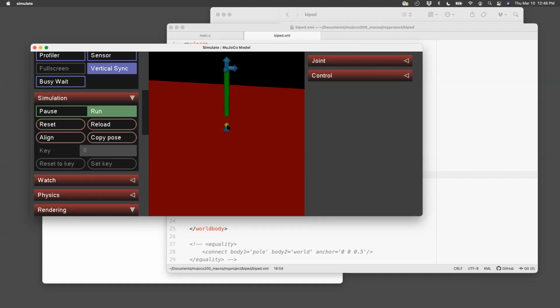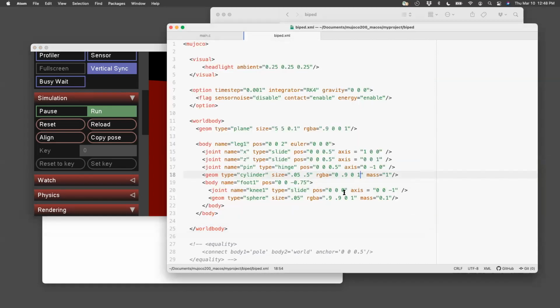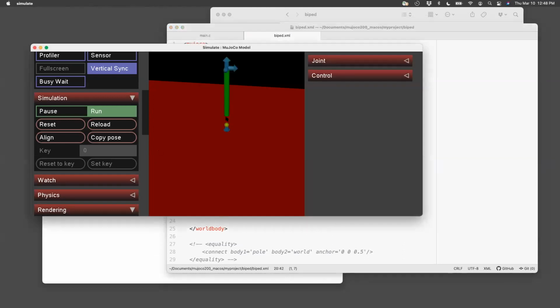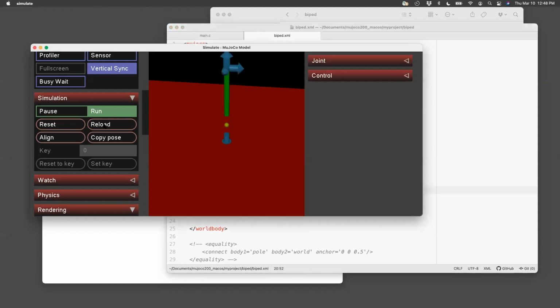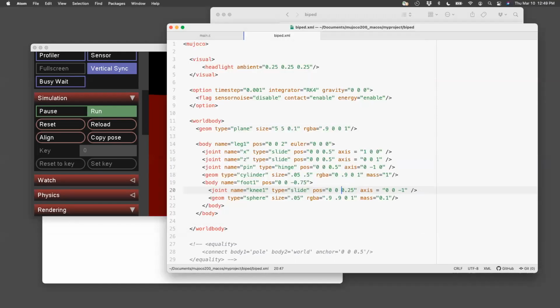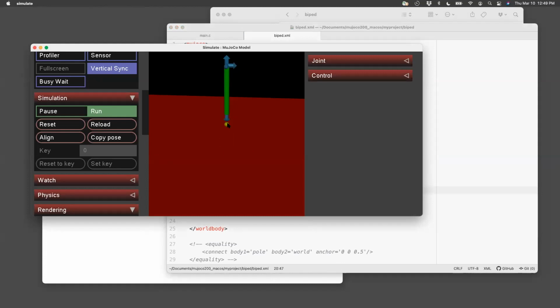It's a little odd that the axis of the sphere is sitting right here. Maybe I want the axis right at the tip of the cylinder. So right now it is set to 0, 0, 0. Okay, but I want it to move up. And remember that this distance is 0.75. So if I want to move it up, I want to probably move it by negative 0.25 because that distance is relative to this point first. And then the other thing is that since the positive axis is downwards, so it's a local axis, I need to do negative and not positive. So let's try minus 0.25 for the joint. Oh, my bad. So it should be positive. Yeah, my bad. The axes are still positive Z upward. So that looks good.